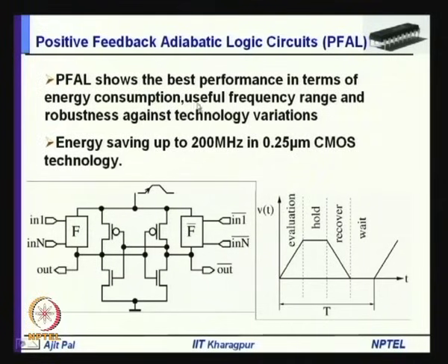PFAL shows the best performance in terms of energy consumption, useful frequency range and robustness against technology variations. So, this has been established by simulation: out of the three members of the partially adiabatic logic circuits that I have discussed, PFAL has been found to work better.